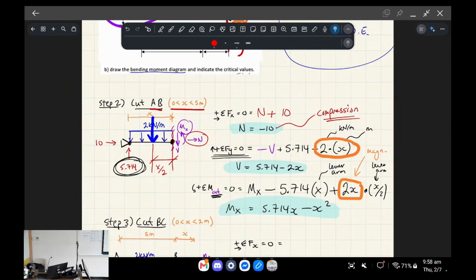The idea with the concept of internal forces and equilibrium is, if I took a slice of this beam and redrew it, that still has to be a 3 kilonewton reaction. How is this beam still in equilibrium, still balanced in some way?